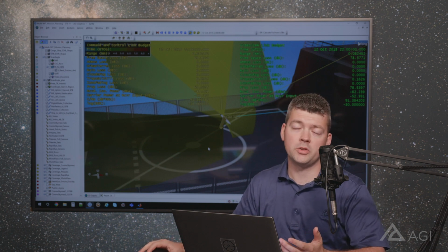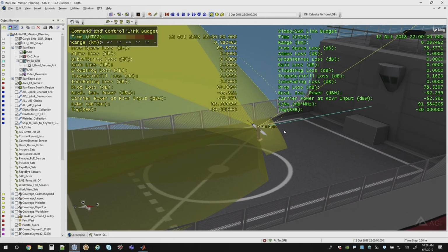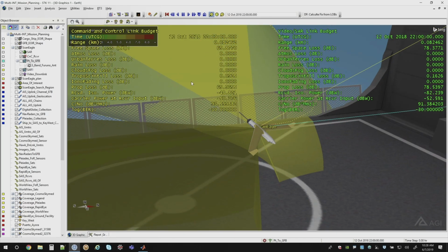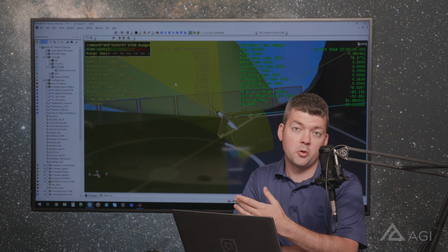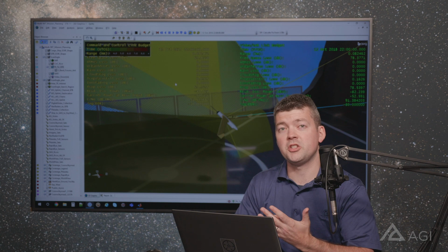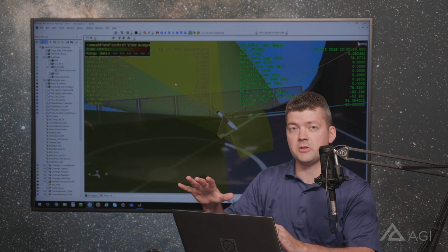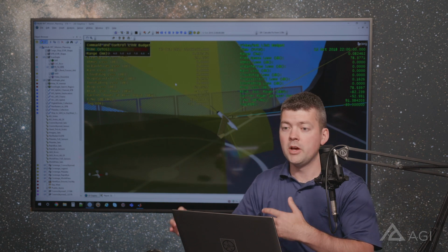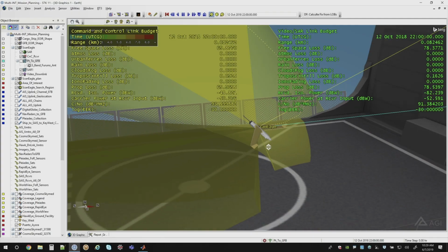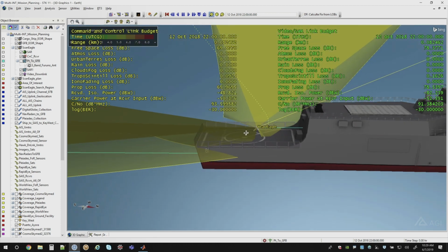So the first thing we want to model is the route of this ScanEagle platform. You can see we're modeling how it launches off at an angle because it's sort of catapulted up. And then using STK's Aviator model, we can plan the whole route according to the performance limits of this UAV. Everything from speed, acceleration, attitude rates, fuel usage, etc. We can tell it, hey, here's my search area of interest. Go make a grid, fly that out for me. So that's what we've done. And then you can see the flight path in dashed yellow coming up here. We've got a few other things as well.